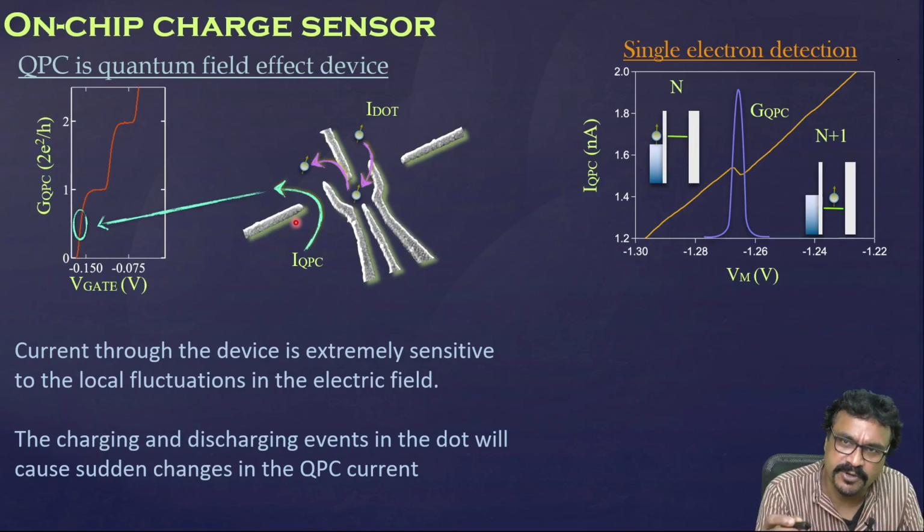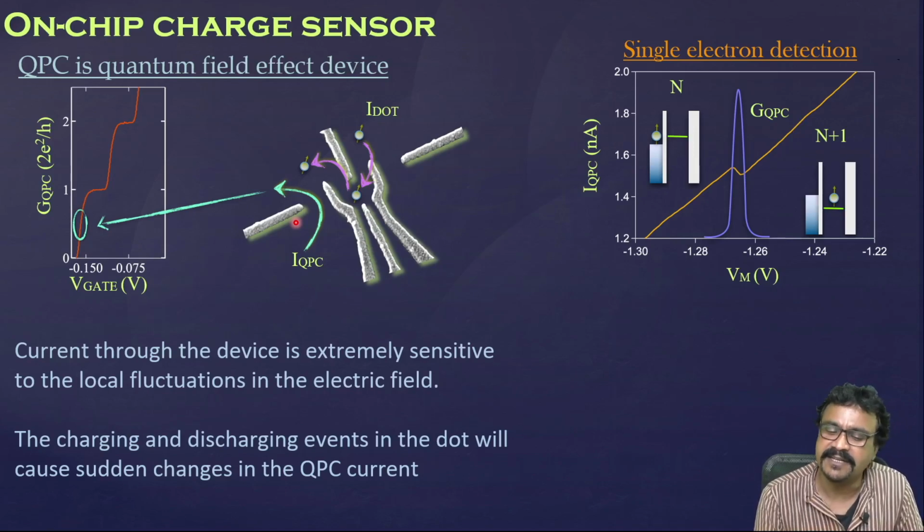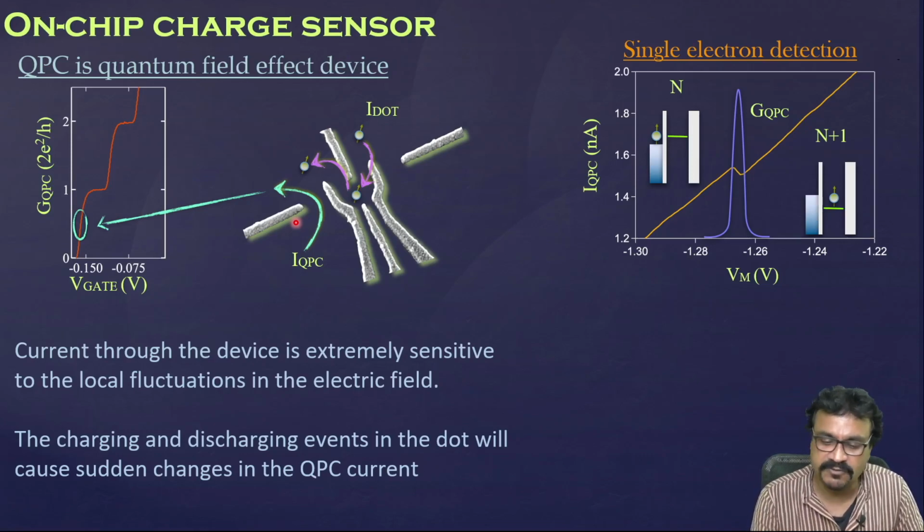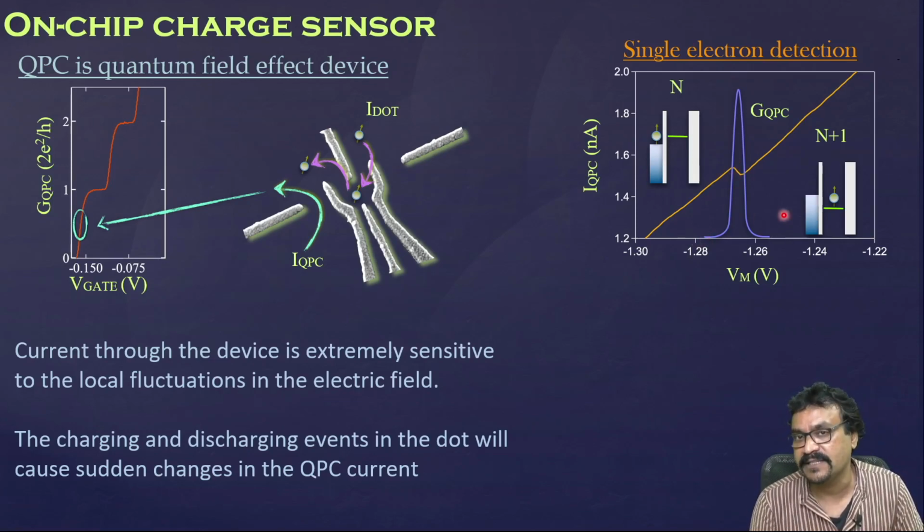This is a quantum point contact, a charge sensor, to check whether the electron is there or not. That is more appropriate, easier, and more robust, because sensing the current does not really work in that regime. So this is what you do. You check for this blip, or the derivative of that blip, which would be a peak. You check for that to see whether there are any more electrons left or not.